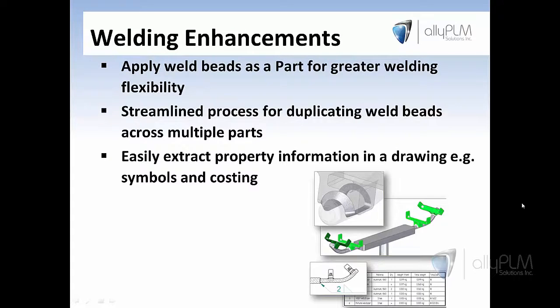We just saw the great new welding enhancements inside of Solid Edge ST8. I demonstrated how to apply weld beads as a part for greater welding flexibility, as well as the streamlined process for duplicating these weld beads across multiple parts. Then finally, we took a look at how easily we can extract the information from a drawing, such as symbols and costing, with this new weld bead information.